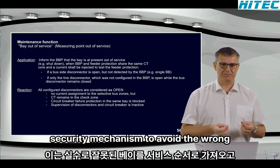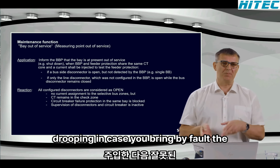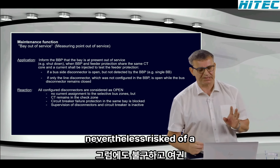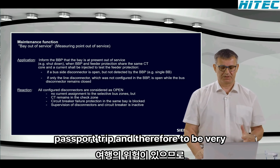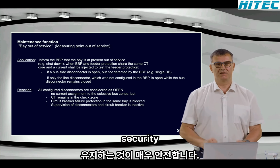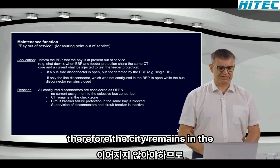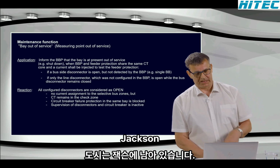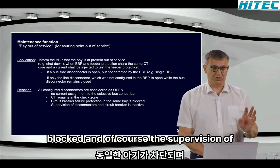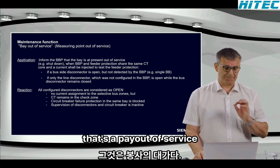This is a security mechanism to avoid a wrong tripping in case you bring by fault the wrong bay out of service and you inject, and then you have nevertheless the risk of a busbar trip. And therefore, to be very safe, to have every time a double security, one fault should not lead to a wrong tripping of a busbar protection, and therefore the CT remains in the check zone. Additionally, the circuit breaker failure protection in the same bay will be blocked. And of course, the supervision of all disconnectors and the circuit breaker is also inactive. That's a bay out of service.